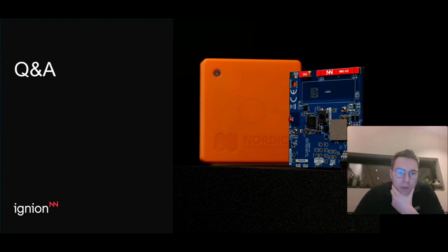It's this: according to the system level design principle, effective isolation is essential for the simultaneous operation of Bluetooth and Wi-Fi at 2.4 gigahertz. While various techniques exist to mitigate interference between these two radios, they often involve trade-offs that impact throughput performance for both Bluetooth and Wi-Fi. Therefore, I would like to understand what constitutes a reasonable level of isolation, as well as the maximum achievable isolation when designing Bluetooth and Wi-Fi antennas on the same PCB, specifically one that is 200 millimeters in length.